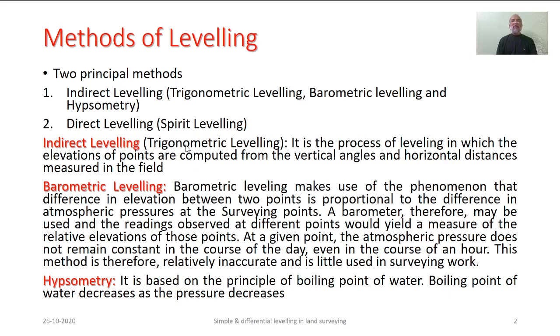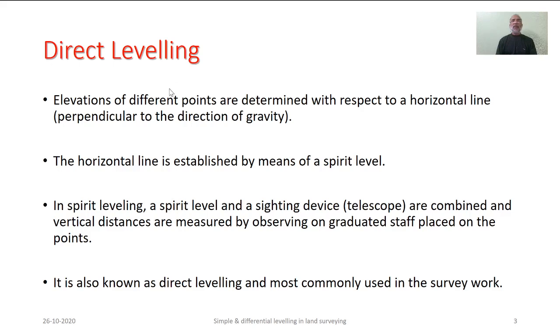We definitely can employ trigonometrical leveling, and I'll be discussing this as you get acquainted with theodolite operations in our subsequent presentations. Now, the remaining part of this presentation concentrates on direct leveling, which is nothing but spirit leveling. In direct leveling, elevations of the different points are determined with respect to the horizontal line.